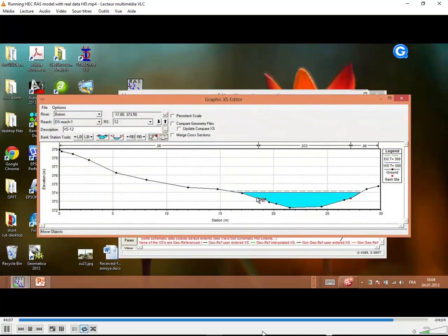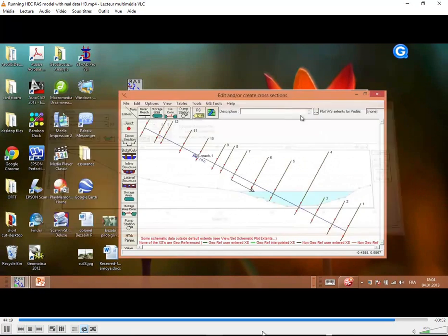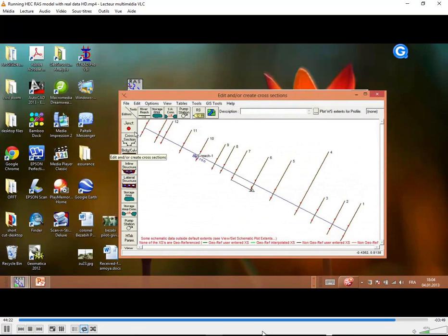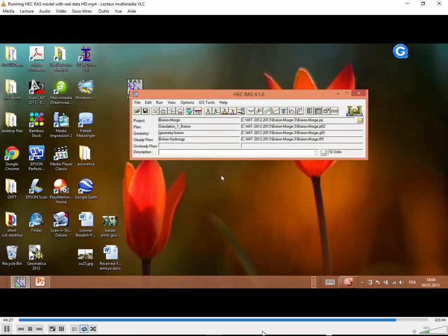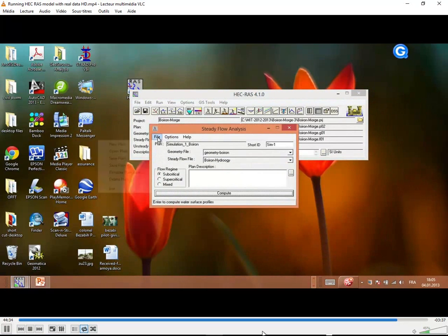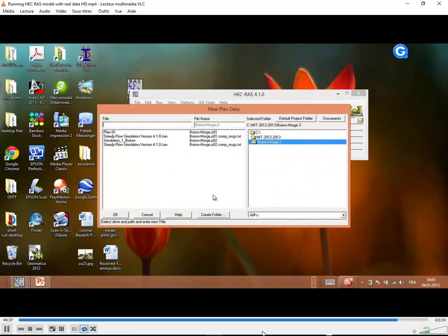Maybe add the, okay, you see, we can add some where the embankment is high, but HEC-RAS assumes only the bank which we have given. So that's how it operates, you see. If we give it an incorrect bank, then the result also becomes incorrect.